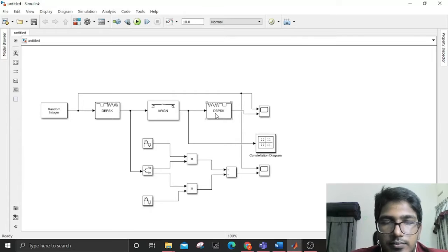In DPSK demodulation block, DPSK signal will pass to the balance modulator and 1-bit delay circuit. The resulting signal is passed to the LPF, which produces binary data. This passes to comparator circuit or schmitt trigger circuit to produce clean and high speed binary levels. Finally, all of these output waveforms will be shown to the user with the aid of the scope block in MATLAB Simulink model.